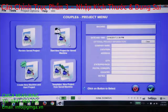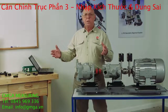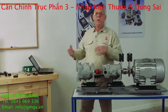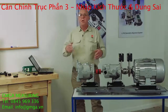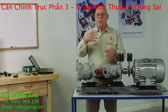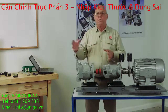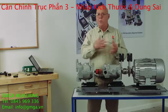I can start a new project for a saved machine. In other words, I've done this before. Now, maybe I was working on it yesterday and I saved it. So I come in today, I can bring this up and I can continue to work on it. We have templates. In other words, I may have done this yesterday and I finished it up, but I want to come back today and look at it again, but I want to do another alignment. I don't care about the data from yesterday. So it'll bring up that template, so all my dimensions are there, but no data.